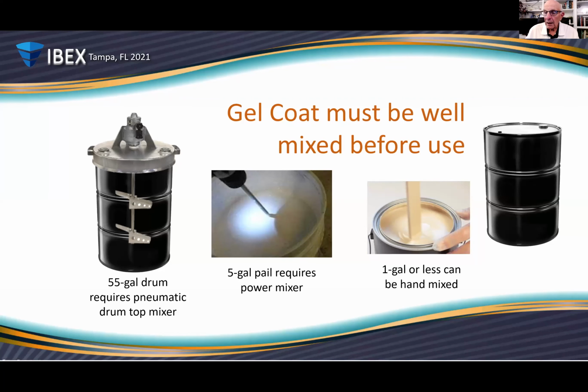So my advice to you is make sure that your gel coat is 100% thoroughly blended before you use it, because all sorts of phantom problems can occur with gel coat if the viscosity or consistency is uneven from the top of the container to the bottom of the container.